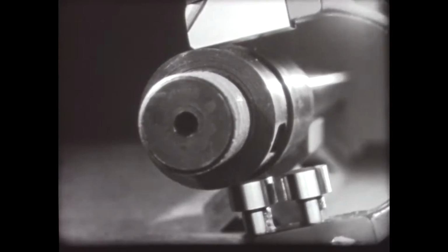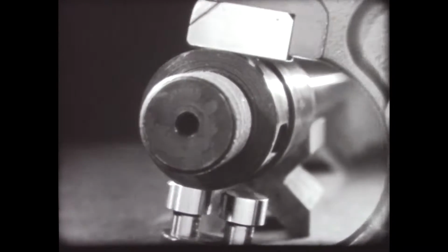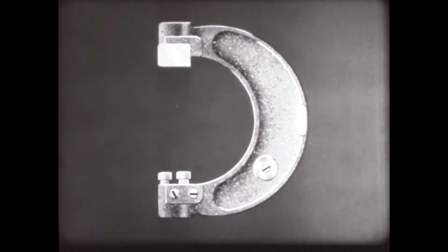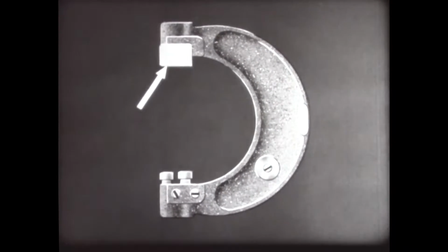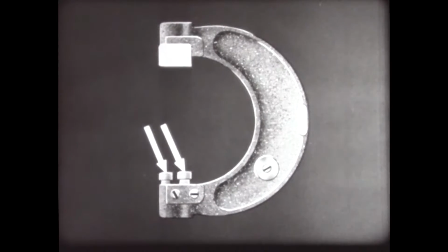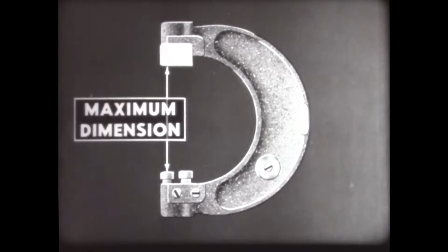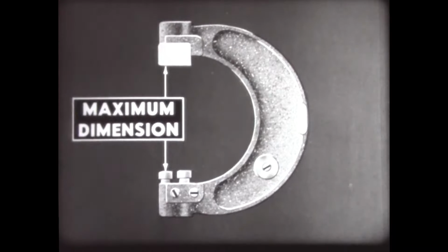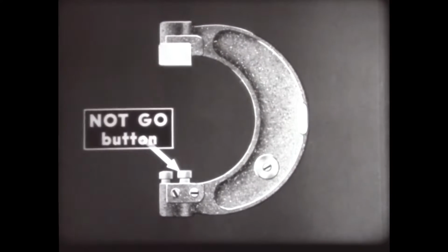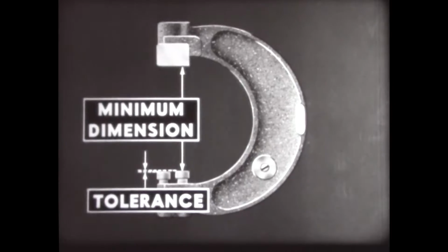Snap gauges are fixed gauges designed for taking outside measurements. They are made in a wide variety of sizes and designs. One of the most commonly used types is represented here. It has a large flat gauging surface called the anvil fixed on one jaw and two gauging buttons in the other jaw. One, which is called the go button, is set at the maximum dimension allowed by the tolerance which is specified for the work, and the other, which is called the not go button, is set for the minimum dimension allowed. The difference between the two is the tolerance allowed by the gauge.